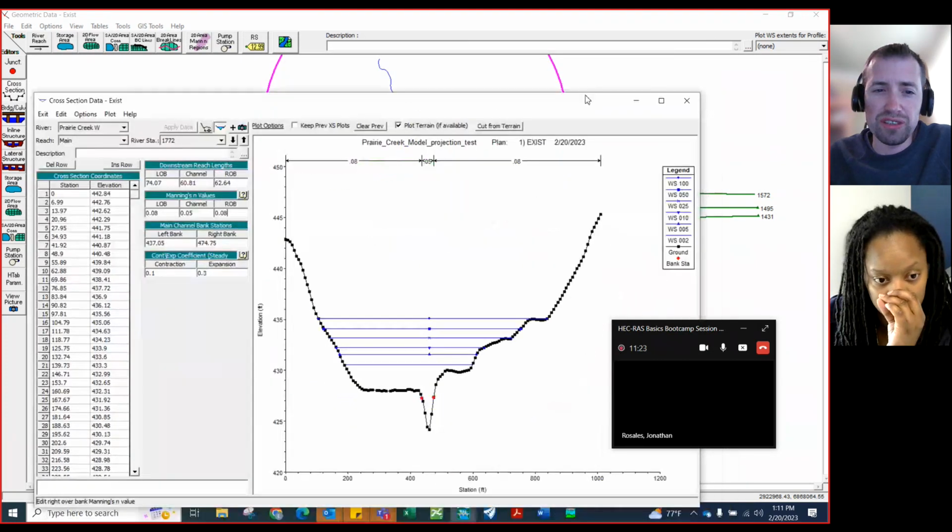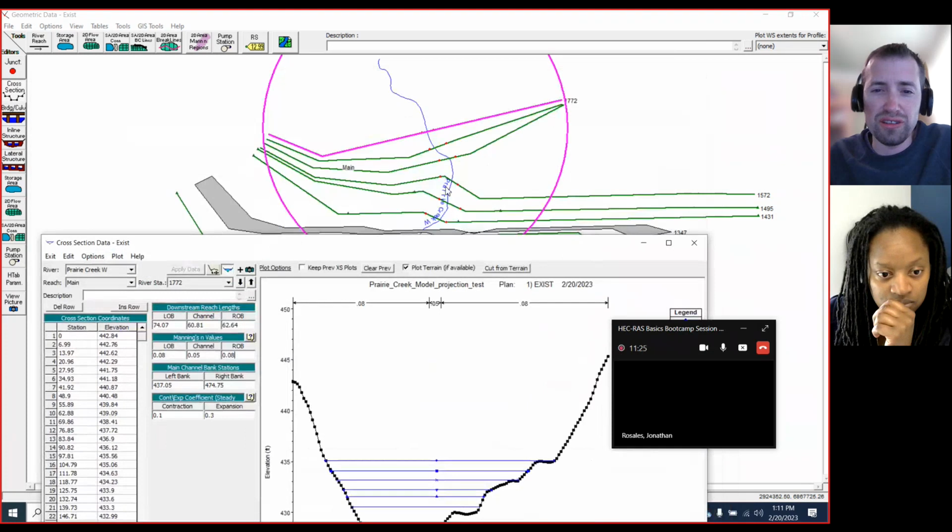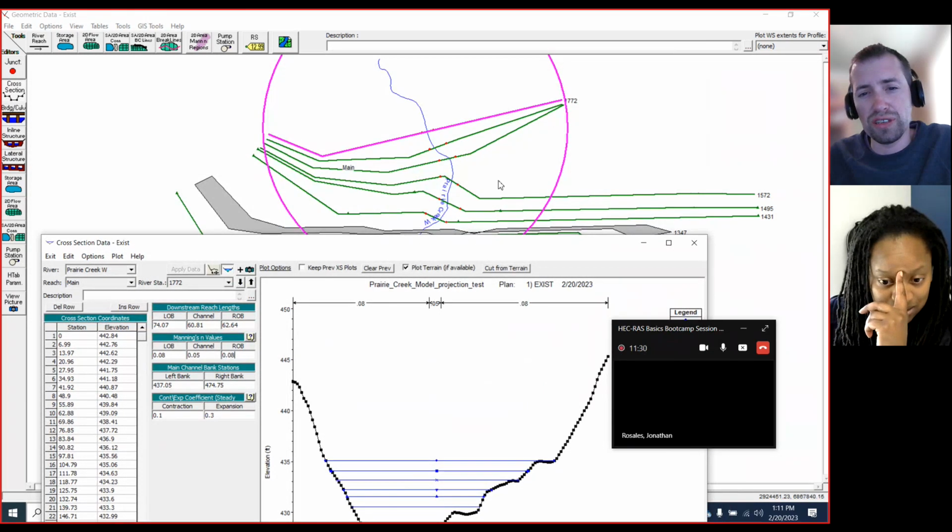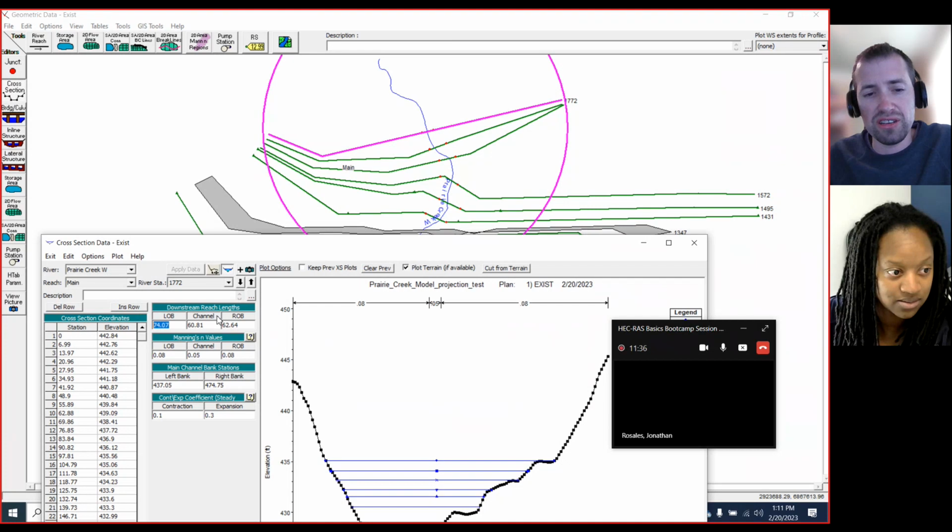And the other item that we're going to be drawing today is your flow paths, and you don't see that anywhere, but with these tools that are used to build the model, what the flow paths do is generate your left of bank reach links and your right of bank reach links, which are right here.